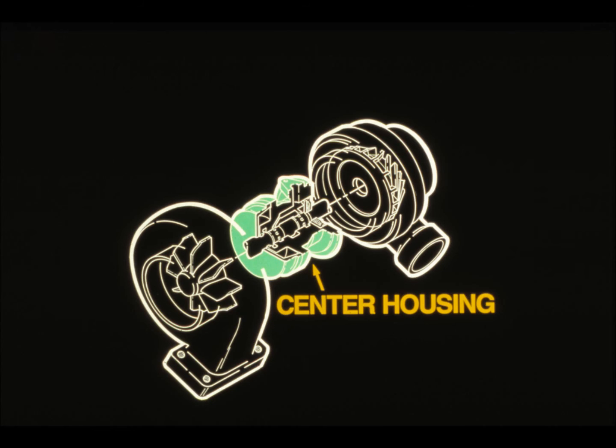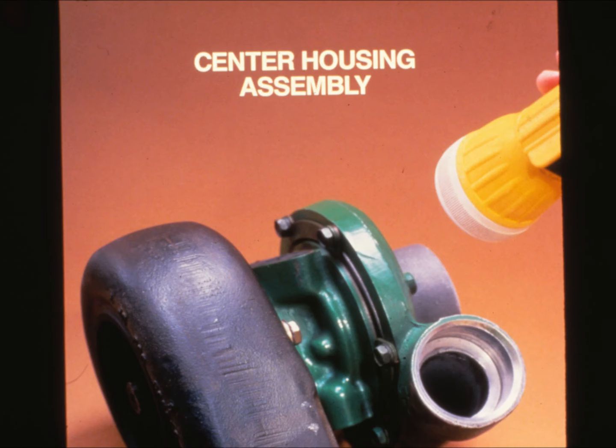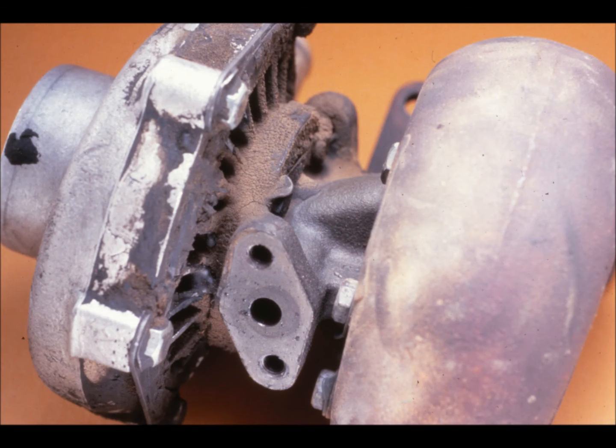The center housing assembly is inspected in steps 5 and 6 of the turbocharger inspection procedure. Both the outside and inside of the center housing should be checked. Step 5 is a visual inspection of the outside of the center housing. All connections to the compressor and turbine housing should be checked at this time also. If oil is present, make sure it is not coming from a leak at the oil supply or return line.